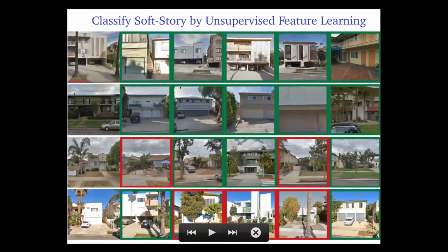Through this, we can get a sense, for example for this one, all the five nearest neighbors are soft story. I can assign a class to the query. I know that in that part of feature space, it has a high density of soft story. So I can have this confidence measure attached to the classification.